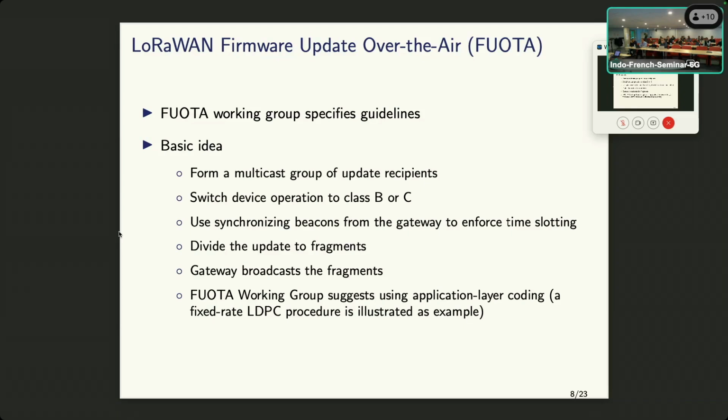In their standard, they have proposed a suggestion, not a requirement, to use an application layer LDPC encoding procedure. All the information packets, or the source fragments in this case, are encoded using an LDPC encoding matrix of some fixed rate, and those LDPC encoded application packets are transmitted using the LoRa communication technology. And as usual, the receiver can decode that LDPC code and find out what the original source fragments are.